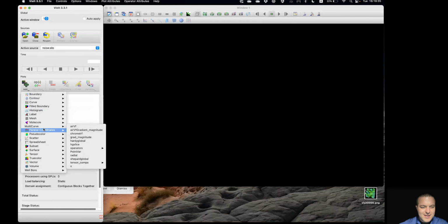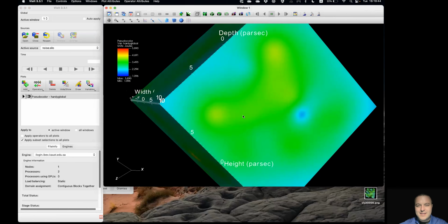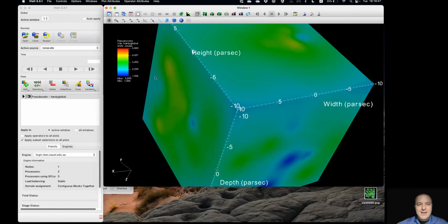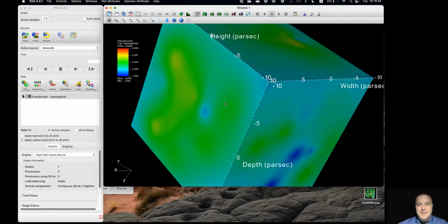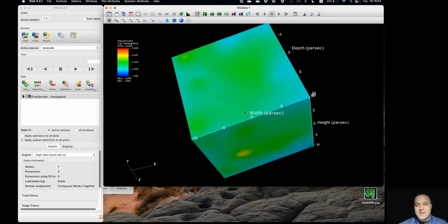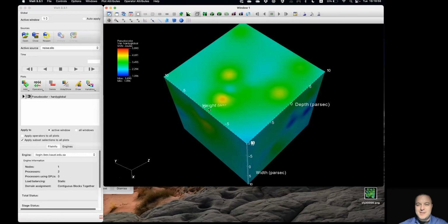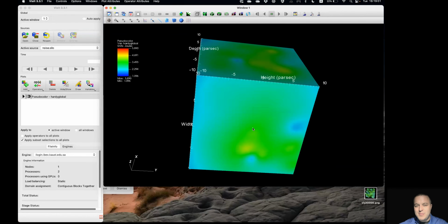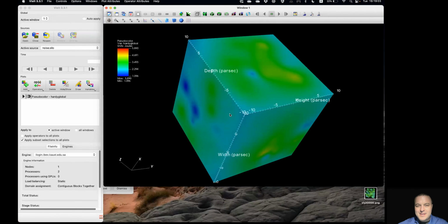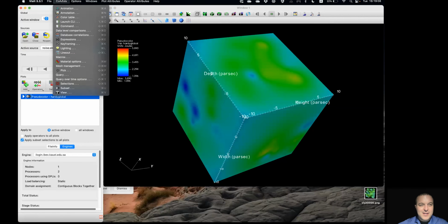It'll work just like it does on your local computer. You can go to Add any of your plots. We'll go to pseudocolor hardy global, click Draw, and it drew almost instantly. So very quick. In this case, VisIt is actually sending us the data from ibex to our local machine, and then our local machine is rendering this image. We know that because the interaction is so smooth. It does that because the data is so small. When you have larger data, it'll actually send you just the images.